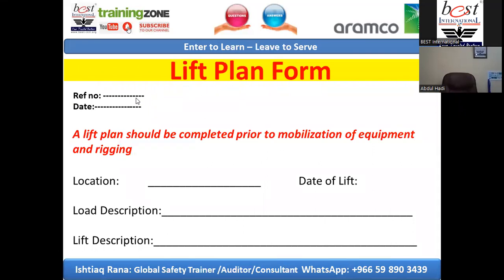So, first of all, we must give a reference number. As I mentioned, we will now discuss the most important practical things, and you need to mention the date as well. Bear in mind, a lift plan should be completed prior to mobilization of equipment and rigging. We need to mention the location, the date of the lift, the load description, what type of load, specifically any sort of item, and the lift description as well.